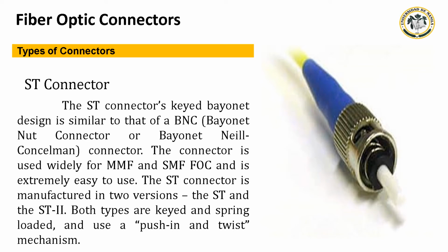The ST connector is manufactured in two versions, the ST and the ST2. Both types are keyed and spring-loaded and use a push-in and twist mechanism. It is typically installed in infrastructure that was built at the turn of the century, and when retrofitting, STs are typically swapped out for more cost-effective SC and LC connectors.